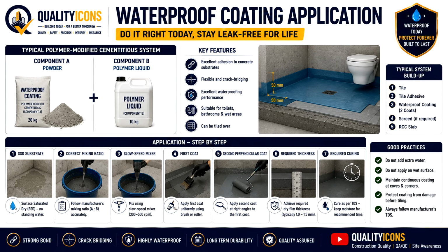Coming to the main step, waterproofing coating application. Do it right today, stay leak free for life. Now the substrate is ready for waterproofing coating. The system shown in the presentation is a typical polymer modified cementitious two-component system. Component A powder, component B polymer liquid.